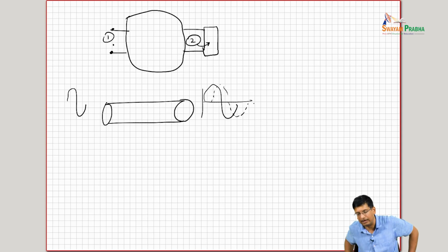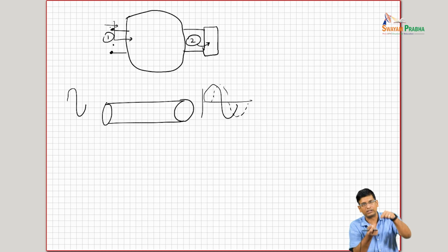Yeah, I mean, standing waves are one phenomenon, right? But effectively, you want to know, and don't think of this only as a real resistance. There is a complex resistance here, so there is a phase between the voltage and the current. So you want to be able to measure the voltage at this node, and you want to measure the current exactly at this node. It's not possible at high frequency for you to access that particular point without the measurement setup itself impacting what you measure.